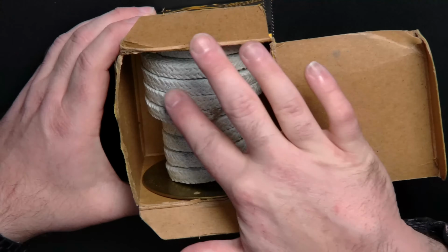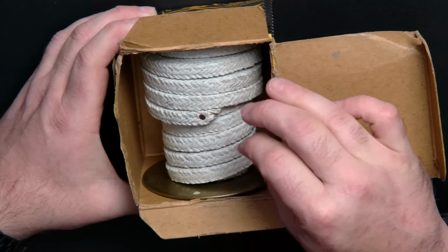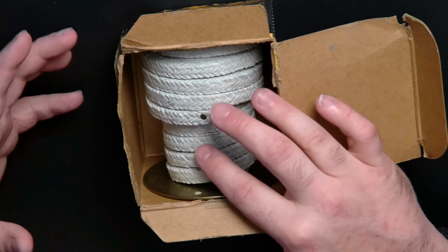Then we go over here on the next slide, asbestos cloth and packing. I wanted to show you, I actually have a sample of cloth that has been turned into asbestos packing. And the same thing applies. As we talked about, very minor, brief exposure I'm not stressed about. I'm not going to take this out of the box and handle it though. This feels like a rubbery, slick kind of coating. And what people would do, my clients, I have a number of whom worked with this stuff, they'd take the portions off and they'd use scissors or snips or whatever and cut it. And they'd pack it inside of equipment that needed this. And then it would be lubricated. And this would help protect the equipment in question.